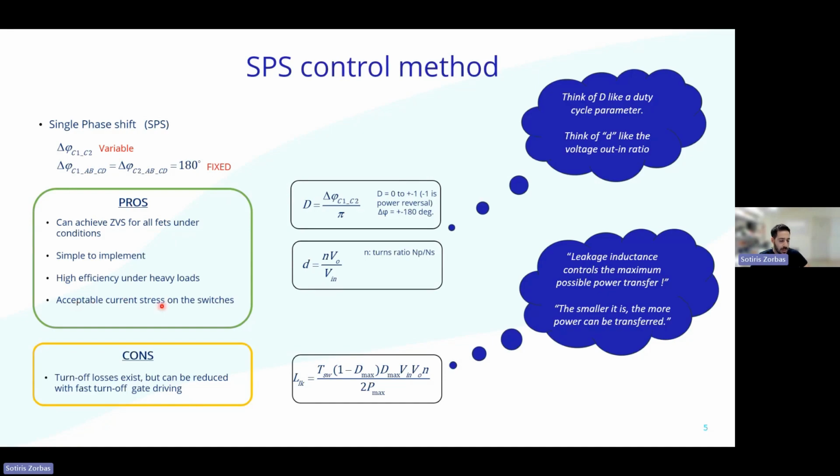What do I mean here is think about, yes, we are in a ZVS condition. Assume that we are in a ZVS condition, right? And then there is the conduction losses. Those conduction losses have to do with the reactive currents inside the bridges, and there is theory, and the theory compares each case. There are different other control methods that are not that good. Other ones are even better. I think they're somehow better than this. This is acceptable, okay, and we will see how.